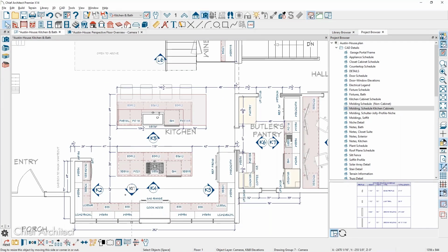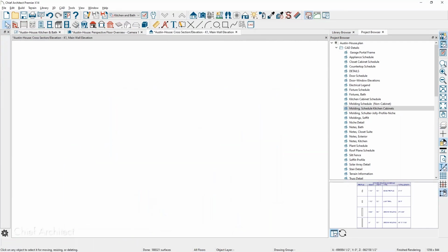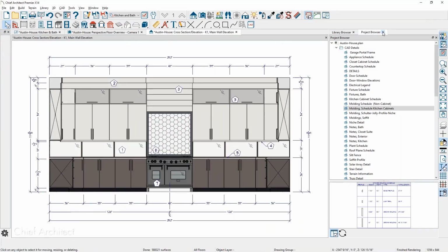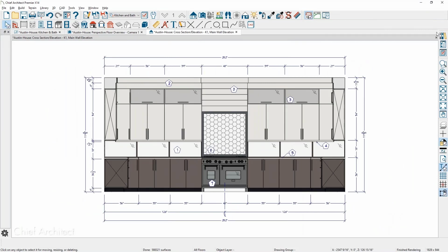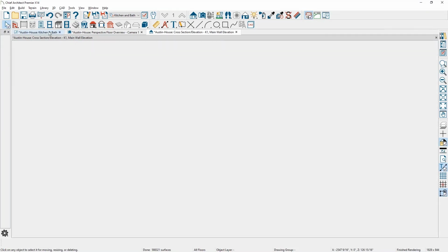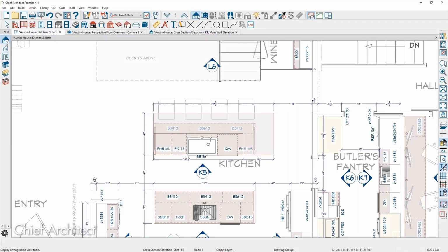When I generate my wall elevations to get something that eventually looks like this, I use the wall elevation tool. When you click on the orthographic tools, there is a specific wall elevation tool. Do you see where it says wall elevation? Is that the tool that you use?